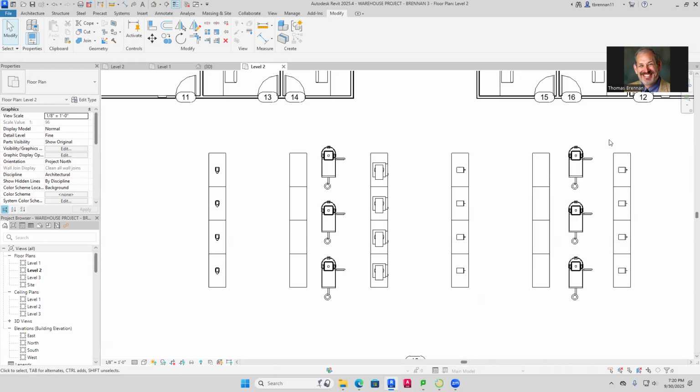So what you've got to do with this is, if it doesn't work, you can just drag these little blue circles to where you want to measure to, and then you just type the value in. Actually, it's always the blue dimensions, the temporary dimensions, those are the parameters. Those actually cause constraints and so forth. Now, the little secret is the black ones can also turn into temporary dimensions, but it's kind of a strange thing because it doesn't always do it. It's almost like it has to be a certain distance. So anyway, you're right on it.